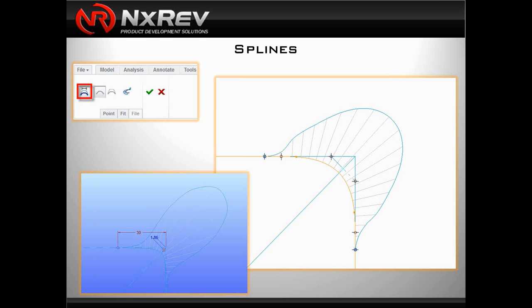You did not have to use those datum points. I just preferred the datum points there because for me it makes it a little bit easier to control the curvature. Also, those datum points could have been datum points from a skeleton model. Don't forget that we had the geometry selection under the spline tool. That is typically overlooked. When this is active, you are able to edit the spline within sketch mode.